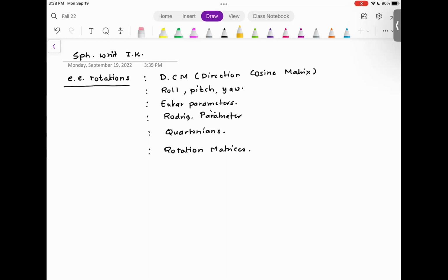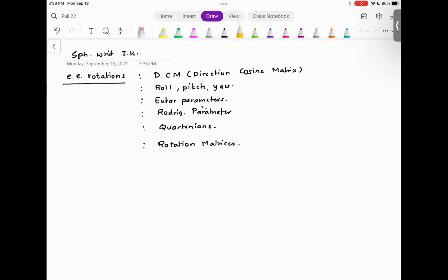So what we will do is, no matter how the end effector orientation is defined, we will use MATLAB or some other mathematical equation to find out the rotation matrix. This rotation matrix will be a fully populated matrix with 9 terms. Some of these terms would be 0, but at the end of the day, this rotation matrix will be a fully populated matrix.